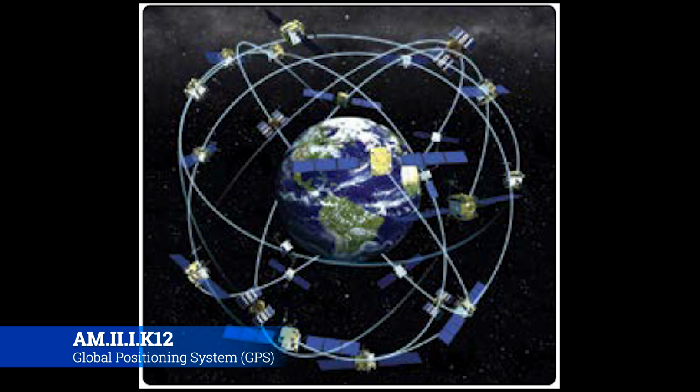You will always have a multitude of GPS satellites, especially now because there's such a huge constellation of GPS satellites up there. That means that the more satellites you have, the greater fidelity you have on the data that's going to determine your position. The more redundancy you have. If one station goes down, you don't lose an entire area like you do with a VOR. If there's one Texarkana VOR and you're only navigating to Texarkana via VOR and it goes down, well, you're going to have to kind of interpolate or guesstimate on how to get there.